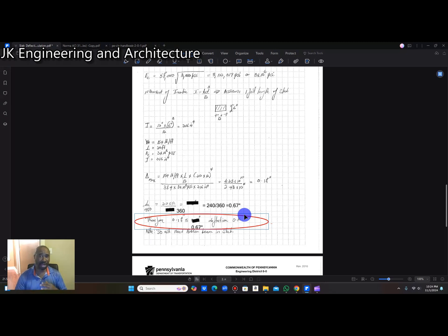In my opinion, the correct thing to do is to calculate the load that is going towards the center and design the beam to carry that load. And that beam has to be a down stand beam, not a flat beam. But what I would say, for a 20 feet by 20 feet slab, even though the calculation is not showing that a flat beam is necessary, I will still put the flat beam at midspan to stiffen that area.